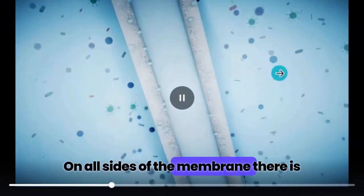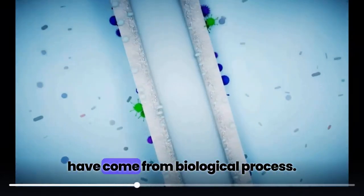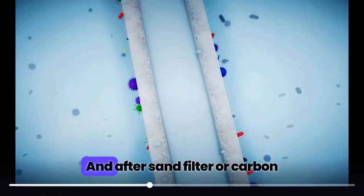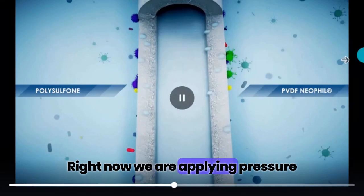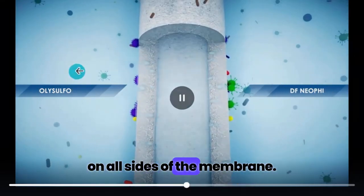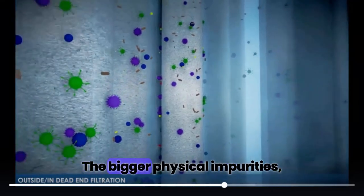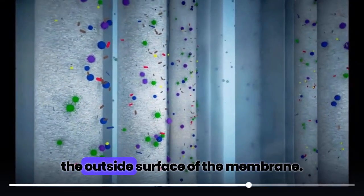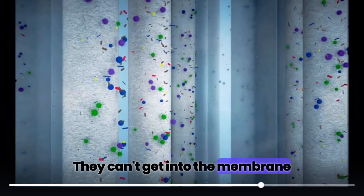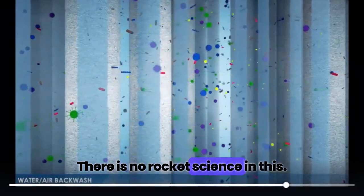On all sides of the membrane, there is raw or treated sewage, which may have come from biological process, and after sand filter or carbon filter, if it is external UF, right? Now we are applying pressure on all sides of the membrane. So due to this pressure, clean water gets into the middle of the membrane. The bigger physical impurities, including bacteria, virus, remain on the outside surface of the membrane. They can't get into the membrane because of the pore size. This is a very simple physical phenomenon. There is no rocket science in this.